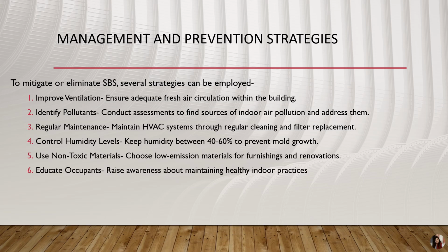Control of humidity level, we should keep the humidity between 40 to 60. If humidity is more, microbial activities are more. If microbial activities are more, there is a growth of bacteria or fungus. Then being in that particular environment, you have fungal infection, bacterial infection, and so on. Sometimes use non-toxic materials like low emission materials, furnishing, renovations.